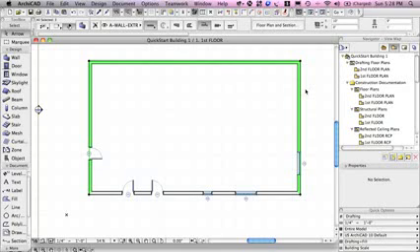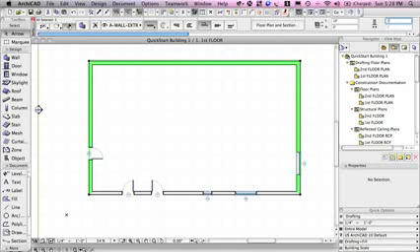Now suppose I wanted to make a change to these elements. I could go in, for example, in the information. Right now it says that it's 9 inches thick, which would be about a quarter of a meter, 250 millimeters. Let me just make it thicker. I'll make it 1 foot thick. So I'll type in 1 foot, and you can see after a split-second delay that the walls have gotten noticeably thicker. So by having them selected, it allows me to modify their settings in the information box,